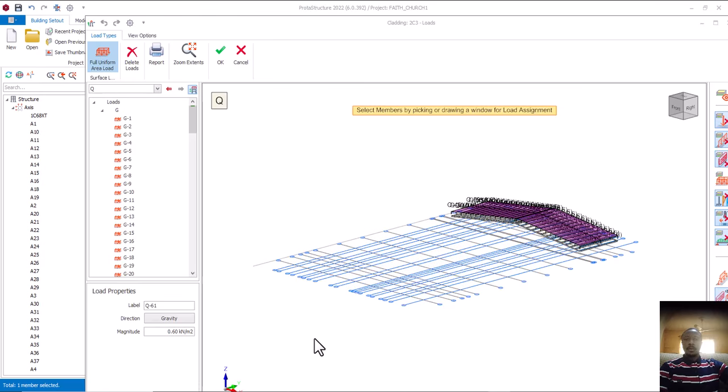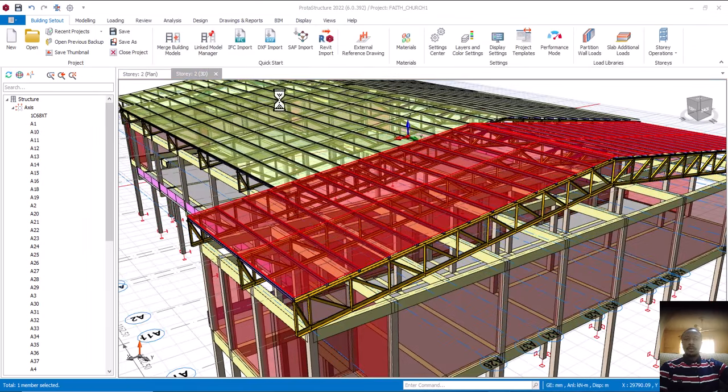Don't forget the way of calculating the roofing sheet is the same. Is that okay? 78.5 kilonewton per meter cube multiplied by the thickness of your roofing sheet. Which you now add to whatever you have gotten from this particular one, and it becomes your total dead load that we are using for this particular roofing sheet. Is that okay? So that is how to go about it. Now, after which I click on OK. I'll click on OK. So that is that.